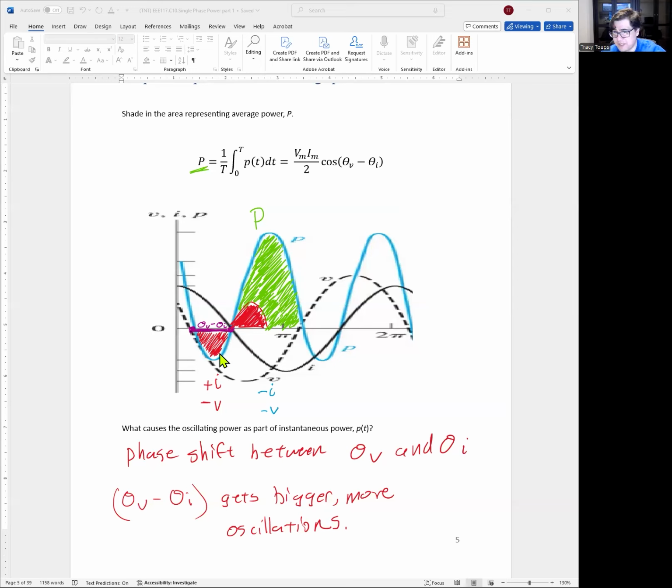Because what's happening electron-wise is, for this negative half, the energy is actually going from the load back to the source. And then in a positive half, some of that source energy that we gave will come back to us. So a little bit of the energy is going to literally go back and forth all day long between the load and the source. Okay. The blue positive, the green permanent energy, that's more of the heater and the loading, the real work being done in the circuit. Okay.